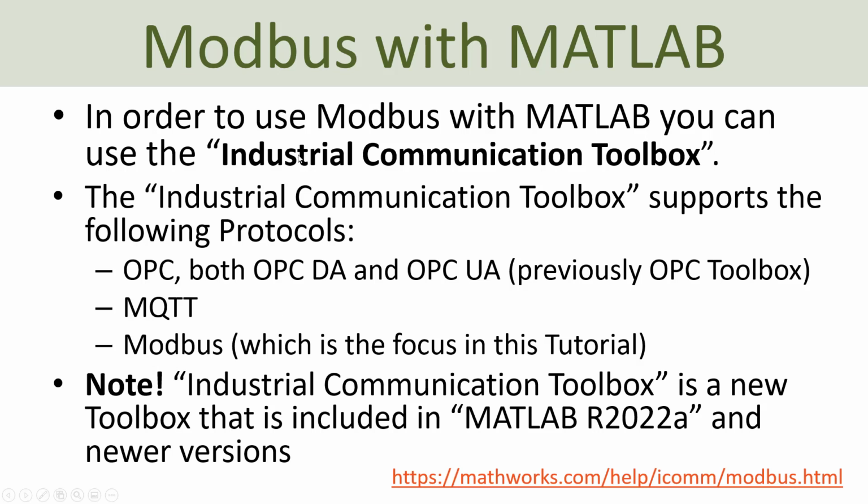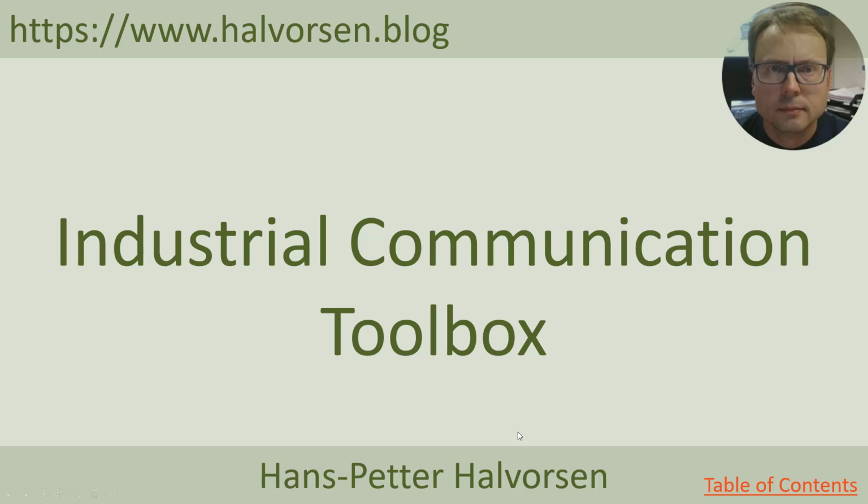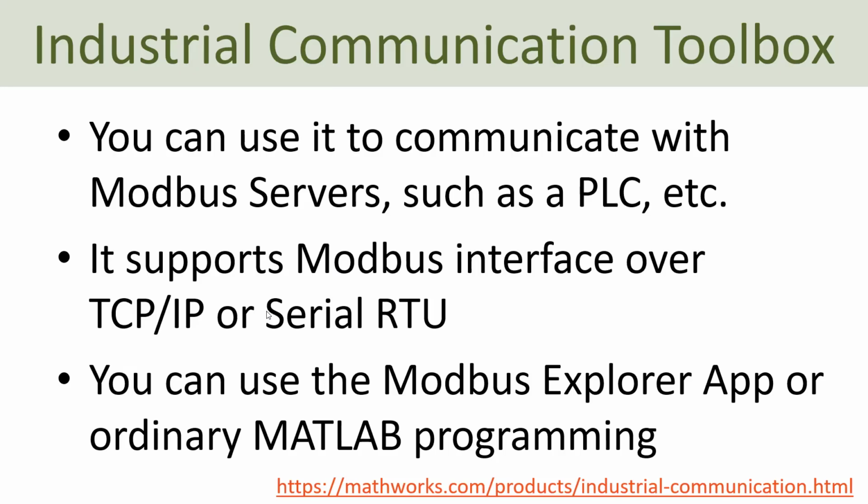So note this is a new toolbox in MATLAB, and it was included in MATLAB version 2022A. So in order to use this toolbox, you need to have this or a newer version of MATLAB. Then let's see how we can use this Industrial Communication Toolbox for communicating with Modbus. Basically, you can use it to communicate with Modbus servers, such as PLCs, or a Modbus server on a PC, etc.